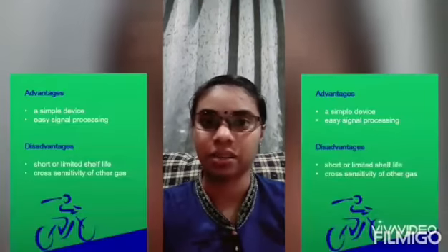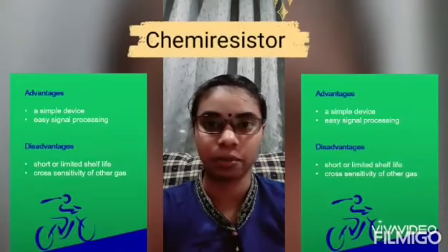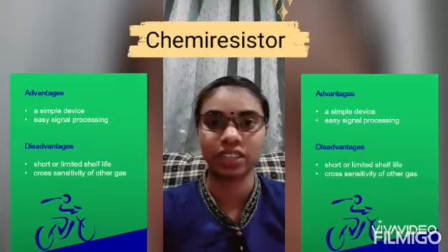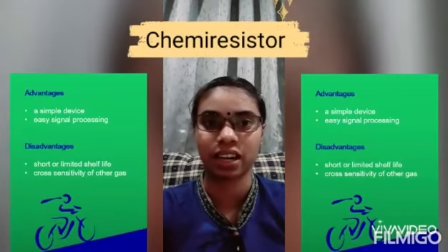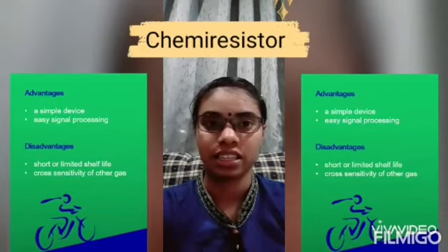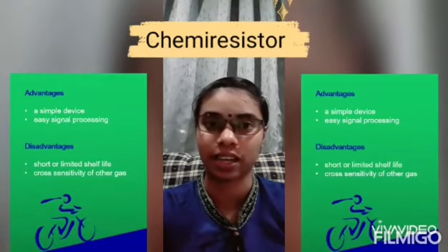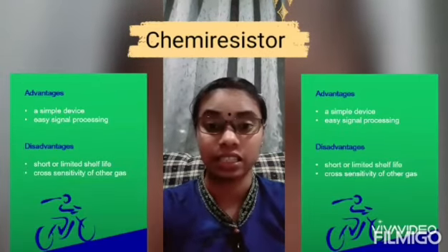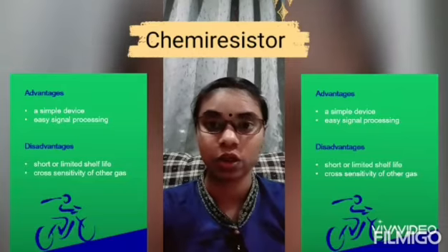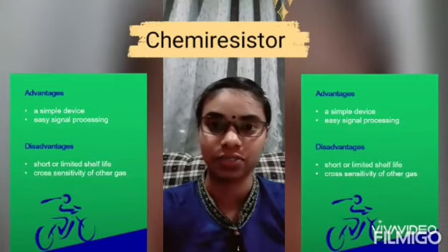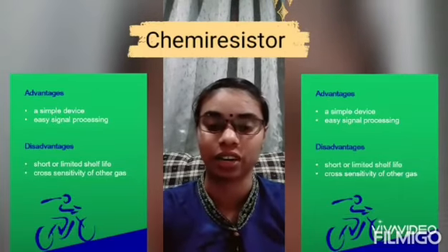Second is chemiresistor. The chemiresistor offers the advantage of a simple device architecture and easy signal processing compared to gas-sensitive capacitor and transistor. The disadvantages are short or limited shelf life and cross-sensitivity to other gases.